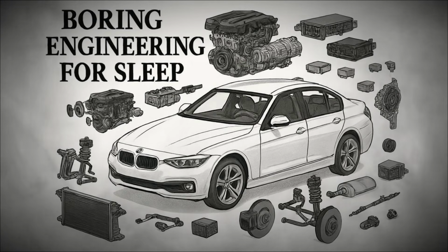Diesel engines operate differently, using high compression to ignite the fuel, but they also rely on a precise injection system that delivers fuel at extremely high pressures to achieve efficient combustion. The fuel system must also manage vapors, since gasoline easily evaporates and creates fumes that are both hazardous and polluting. Modern cars are equipped with evaporative emission control systems, which capture vapors from the tank and store them in a charcoal canister until they can be burned in the engine.